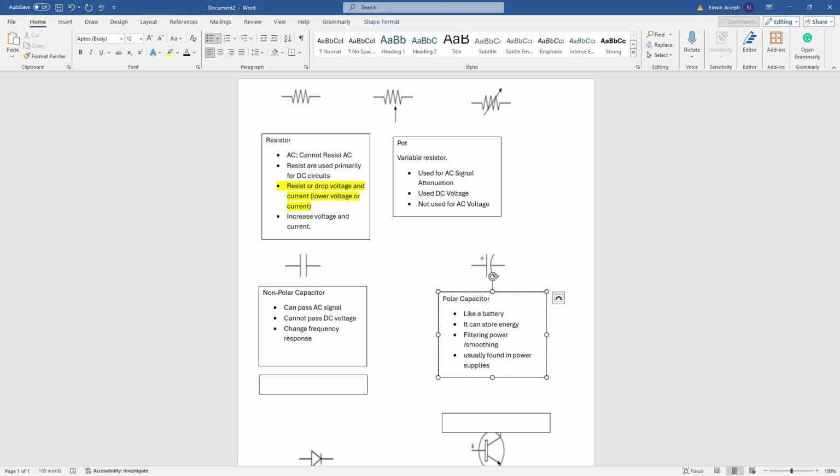It could not be. Like I said, not every circuit is so demanding of energy that it needs the capacitor to hold and discharge it and all that. Primarily, they're used to smooth out the DC signal after it's been rectified from AC. When I say rectified, I mean converted from AC into DC. After an AC signal's been converted into DC, it usually needs something to smooth it out. If you're not aware, the signal can be, we call it dirty, right? It can be not very clean, so we want to smooth it out. We talk about smoothing it out with a capacitor.